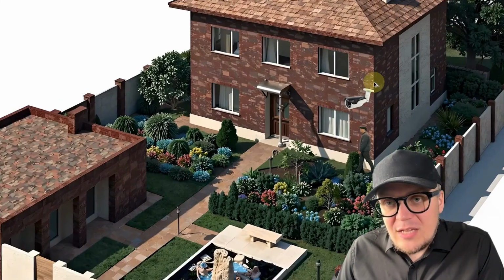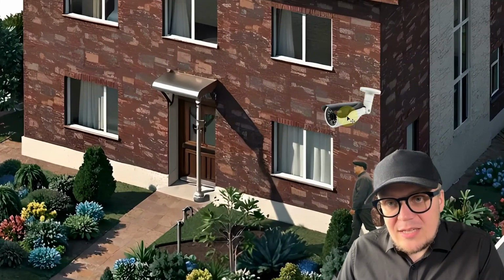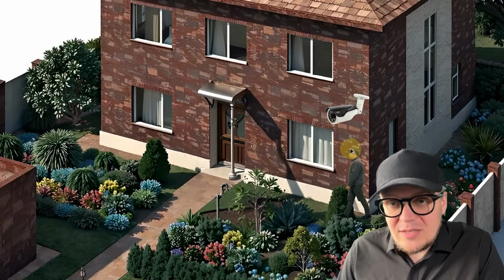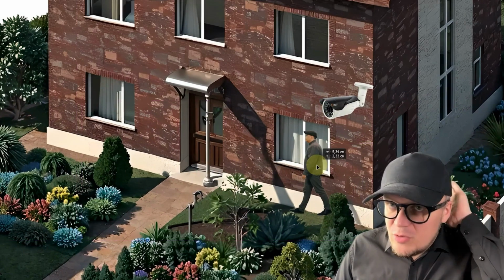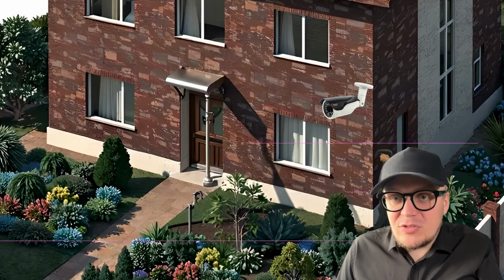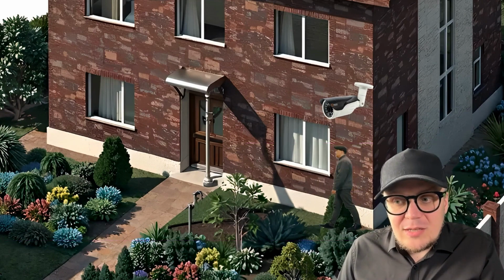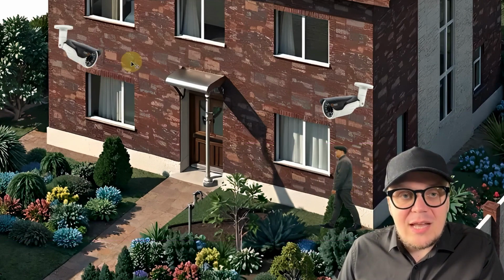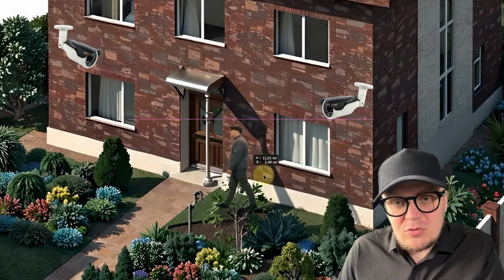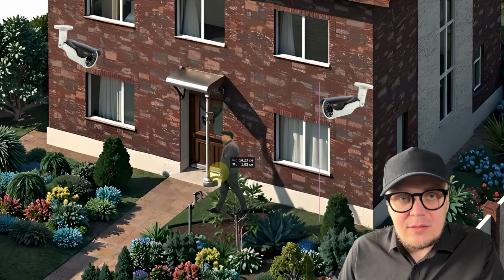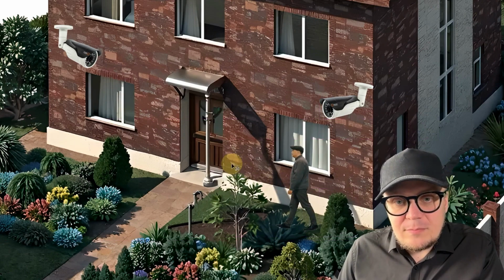The first common mistake is when you install the surveillance camera like this. What is the mistake here? It's that from below, a person and faces won't be seen, you will only see the back of the person's head. How to fix this mistake? You need to install a second camera facing the other direction. Then, no matter how a person passes through this area, you will see their face in any case.